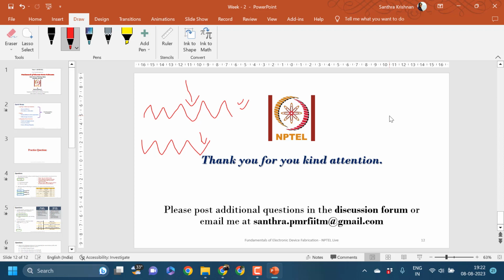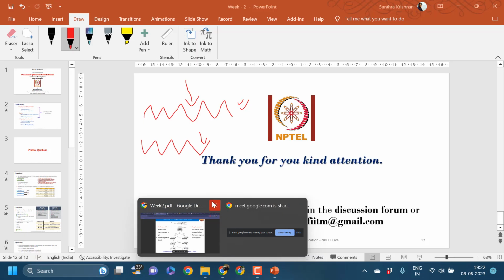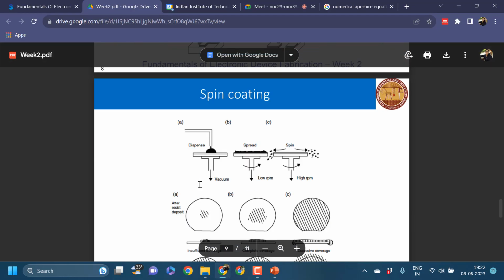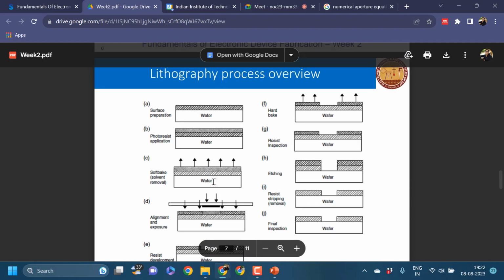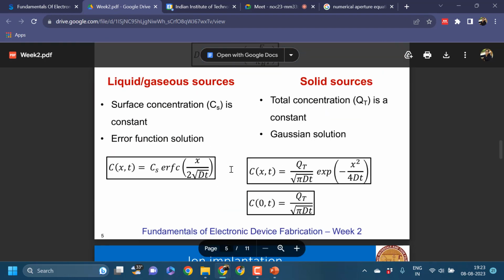Ma'am, for knowing more about that thermal oxidation process, there is one model, no, in which there are bulk concentration and other terms. Okay. The part I asked you to find out, like why wet oxidation. Thermal oxidation, in that, how it is governed by Fick's first and second law and how we arrive at those equations. Are you asking that one? This part are you asking?